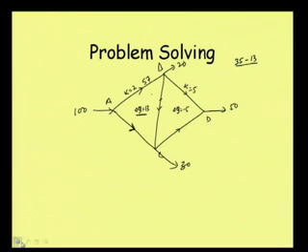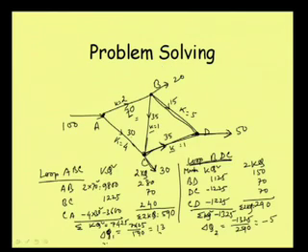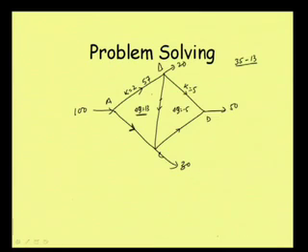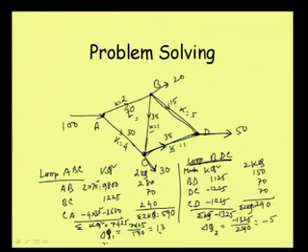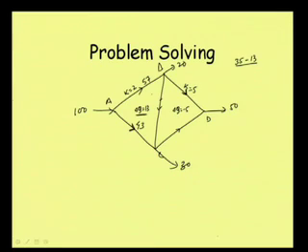If we add this 13, then earlier this flow was 30, so now it will become 43. Similarly, in this loop the correction is minus 5. Earlier this flow was clockwise, so since the correction is minus, we will have to add to the clockwise flow. The first assumed flow was 15, so now this flow will be 15 plus 5, that will be 20.